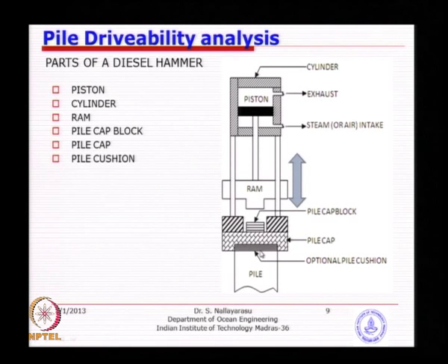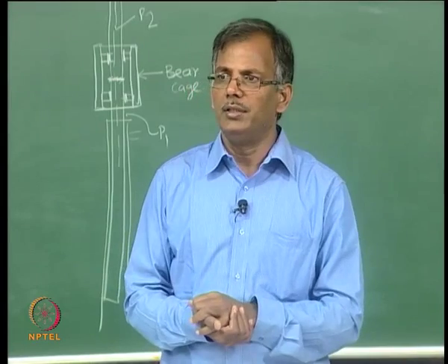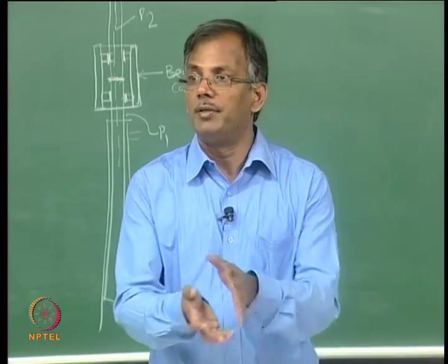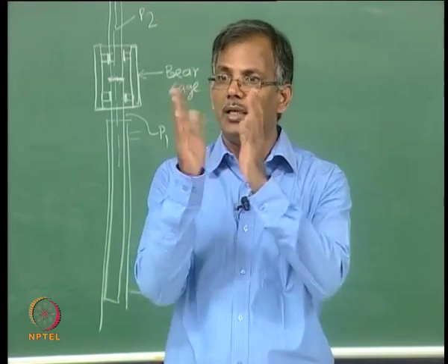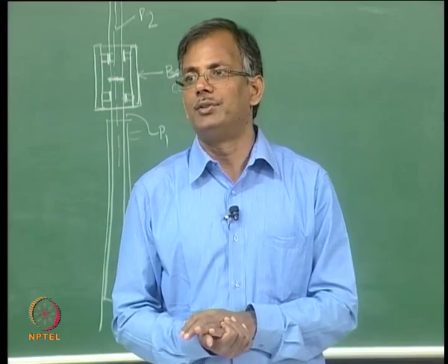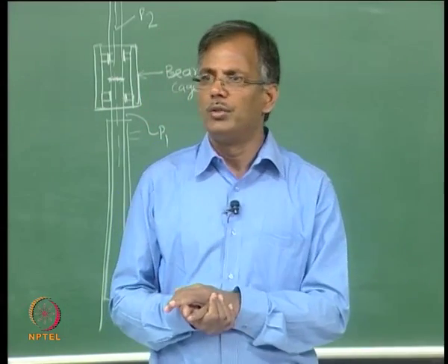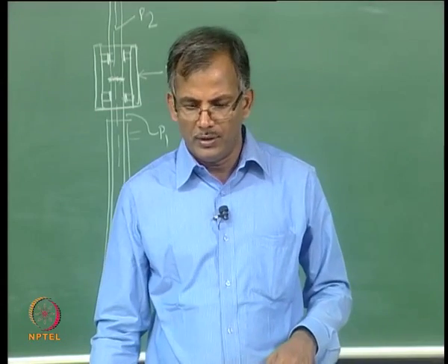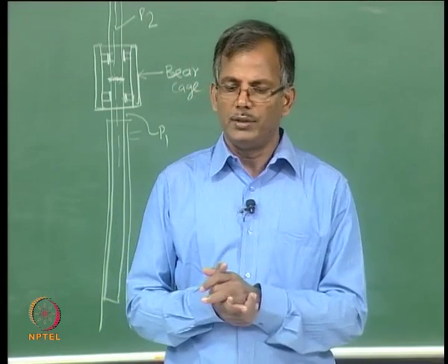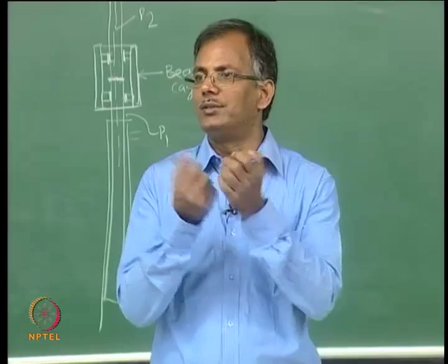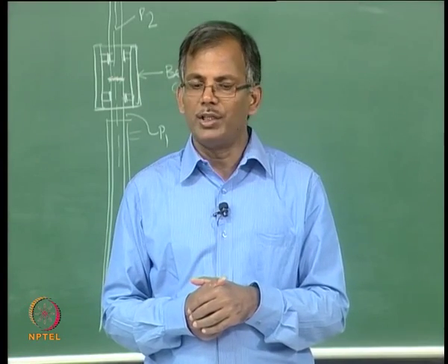You might see in many places the material that can absorb a reasonable amount of energy, but not too much, because if it absorbs too much energy, then the energy transmitted to the pile will become too less. So normally we use wire meshes or soft wood placed on top of this pile, so that it does not damage the pile edges or pile wall thickness.